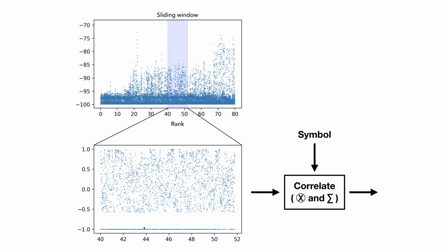So there should be just one value for each of these, and that helps smooth out the distribution so that these powerful transmissions that happen don't blow out our correlation, don't add too much weight to our calculation when we're correlating and summing these values together. It sets everything back down in the space of -1 to 1, and so these powerful transmissions now have less impact on the calculation.